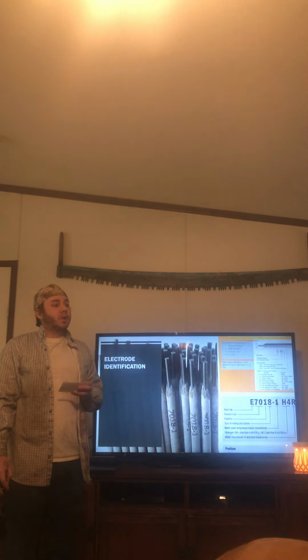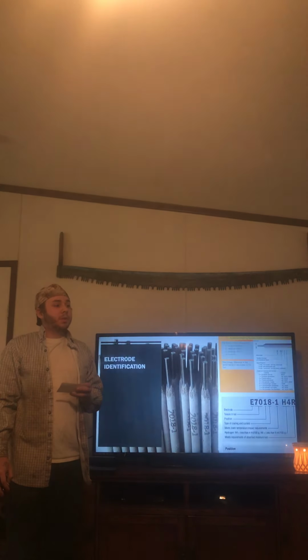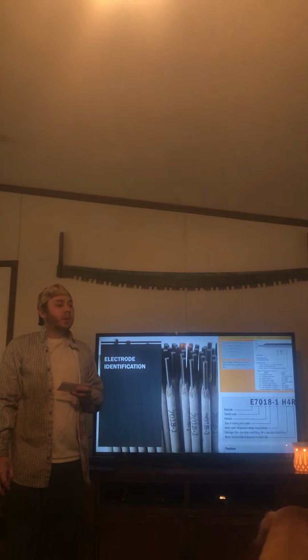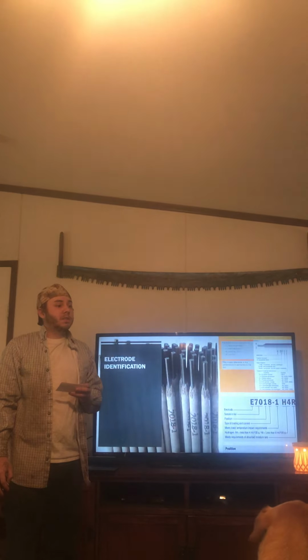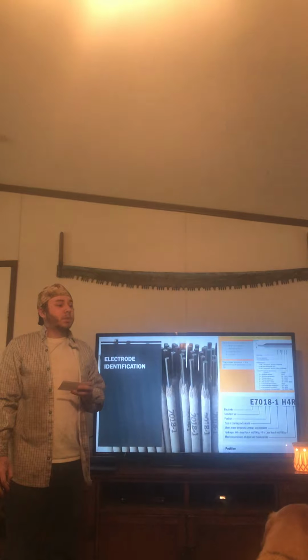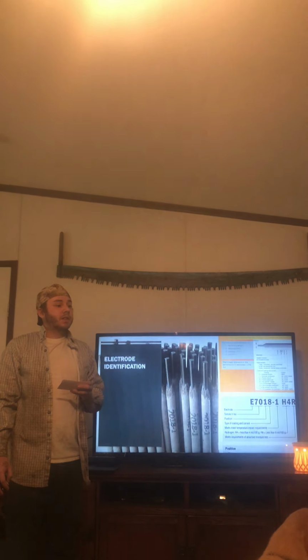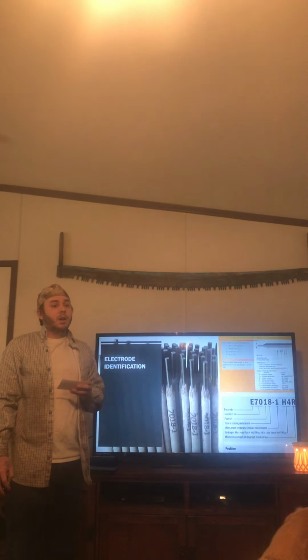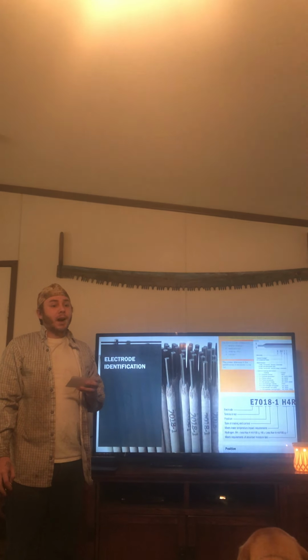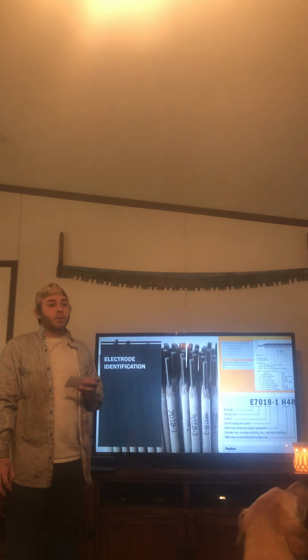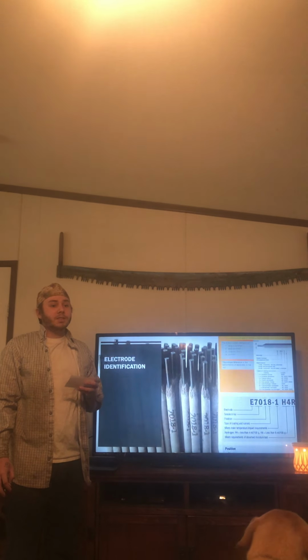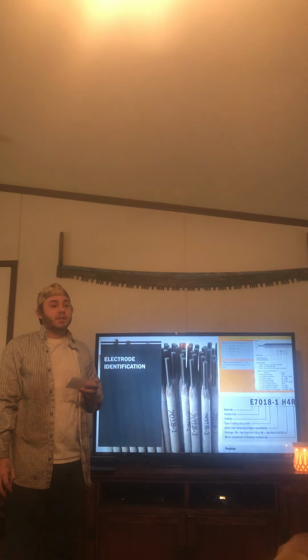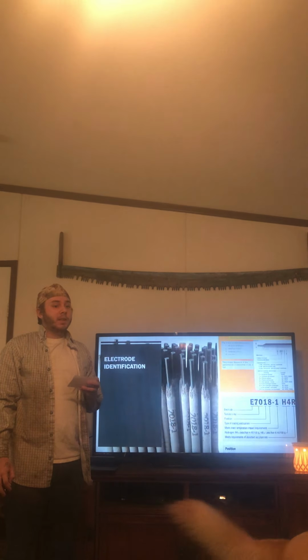The E7018 is a low hydrogen iron powder type electrode that produces high quality X-ray welds. It can be used in all positions on AC or DC reverse polarity welding current. It is recommended for welding medium grade carbon steels, normally exhibiting excessive porosity when welded with conventional electrodes. Typical applications are low alloy structures, low, medium, high carbon steels, offshore rigs and power plants. Steel structures, tack welds from tubular wire applications, and then we move on to E6010.